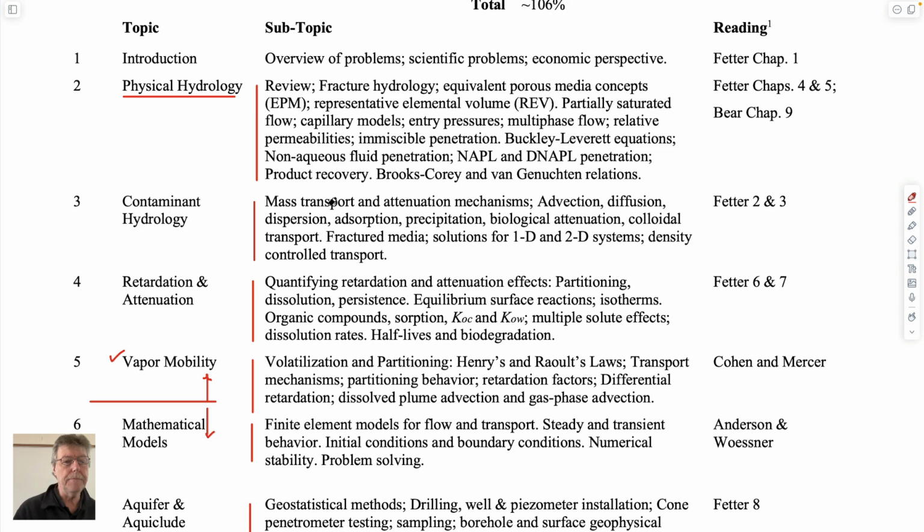So you know what we've done so far. I guess we are right here. And you know what we've been doing. We talked about multi-phase flow of two fluids, capillary pressure, saturation curves, and relative permeability curves to see how multi-phase fluids end up in some location, chimney, a puddle underneath the chimney, and then is held there by capillary forces after it gets there, maybe in a few months, but then is held there for perpetuity. It wouldn't be a problem if they didn't dissolve in small concentrations and were hazardous at even smaller concentrations.